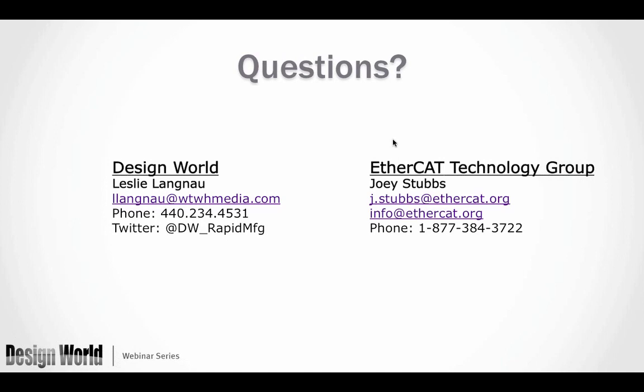Another question here is, what makes EtherCAT's version of the DC more precise than the IEEE sync standard? Well, I think the specification for IEEE has several versions. So the typically implemented IEEE 1588 in industrial communications, at least in industrial Ethernet, does not go down to the nanosecond level. It's tied more to what's going to be serving up the real-time clock. Whereas with EtherCAT, some of the benefits are that this is already built into these chips, which can cost as low as $5 in the slave devices. And so there is no extra hardware to add, such as 1588 support on the slave devices, which requires extra hardware.